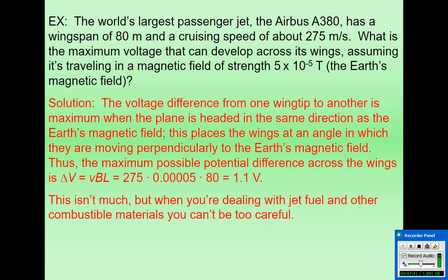And that's not much, but when you're dealing with jet fuel, that's an issue. And furthermore, and this is for complicated reasons, the buildup of charge doesn't necessarily entirely separate once the plane comes to a halt. Sometimes some spots will build up charge, and then that charge will remain there even while the plane is stationary. And so you've got to be really careful about that, which is why when you start operating on planes' wings and stuff, typically you're grounded.